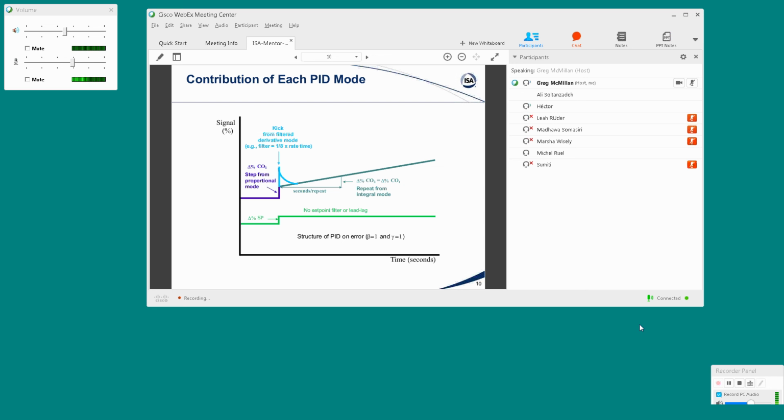And then there's another option, which I didn't mention. This is what Shinsky says, and this is a trick, I guess, for the furnaces that couldn't do that because it wasn't fast enough unless this would be done programmatically. If you put the controller in manual for a second and make the output change, it could be a few seconds for a lot of cases, but for those furnaces it would have to be a fraction of a second. You make an output change, you put it right back into auto, and you can see what the response is. But I think the software today can do identification from set point changes. It can also inject output changes with the controller in automatic, so you don't have to put the controller in manual to get these classical responses that I showed in those slides.